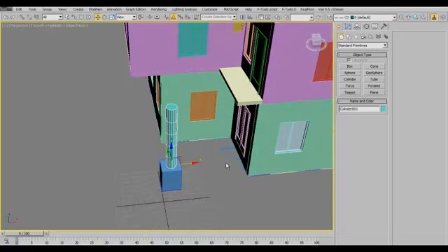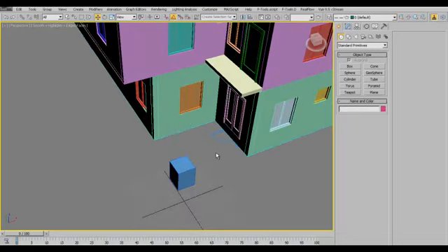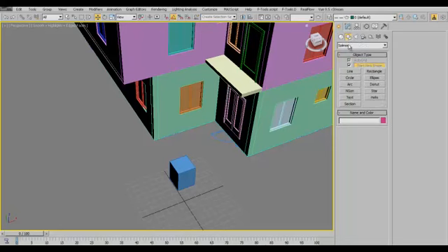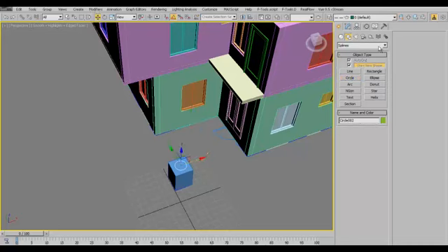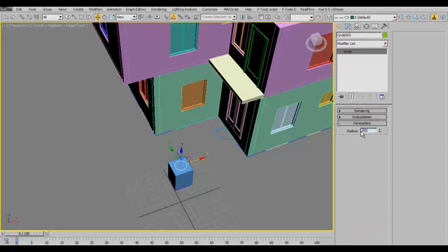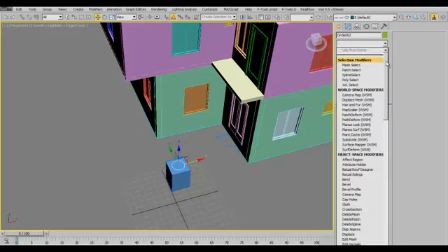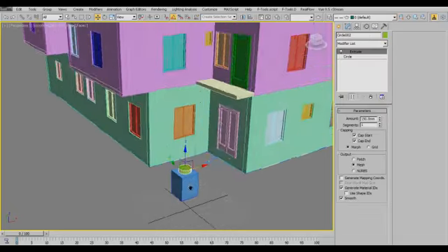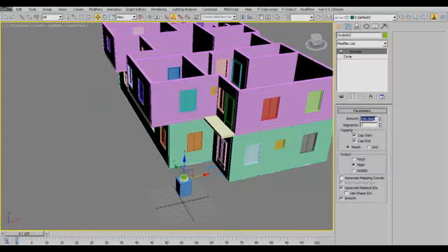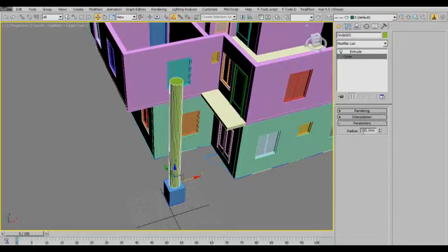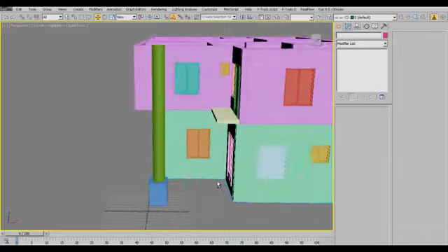So this is there, but I want to use a spline to create this, which is a circle. So just show you a couple of things. A circle with a radius of 250. Good. Then we now apply our extrude modifier, which, let's see the height of our thing. That's 5,600. That's 5.65600, and I think we might want to increase the radius a little bit, and I think it's good. We have a good enough radius.